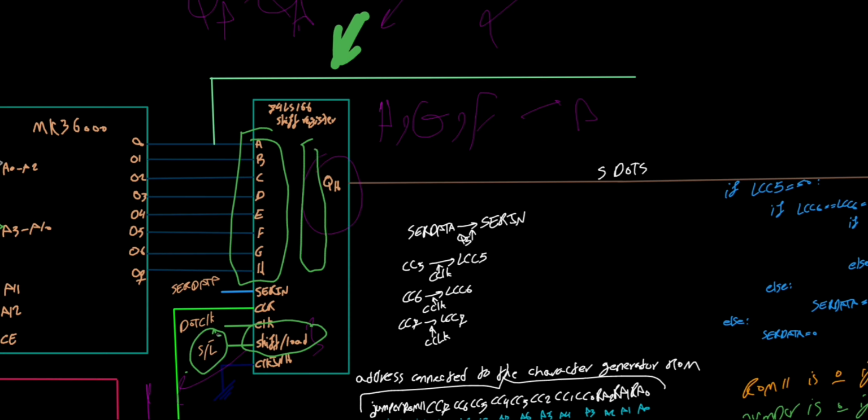But then for 8 clocks, the SL would be equal to 1, and on the low to high transitions, the value that we put on the QA to QH would travel, and therefore QH at 1 clock would have the value of H, on another clock would have the value of G, on another clock would have F, up to the value of A.